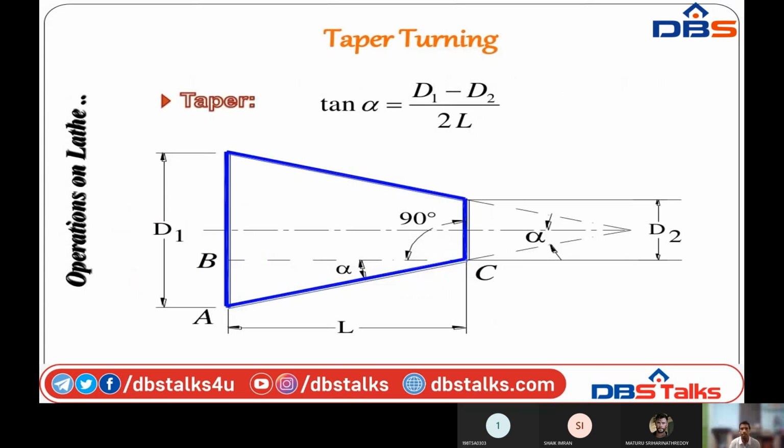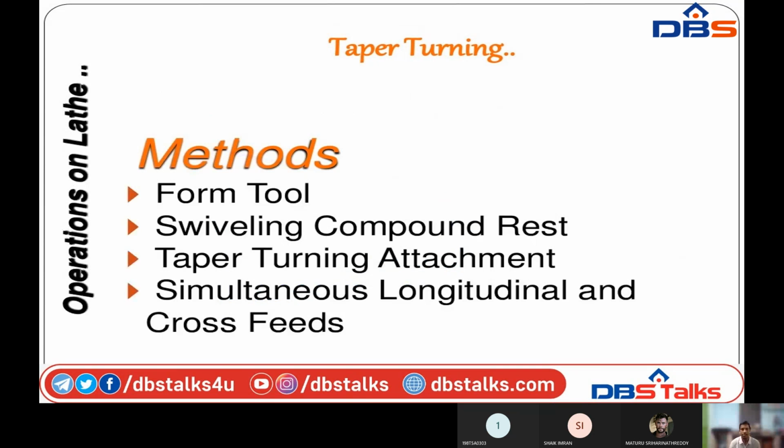Taper turning. Previously I discussed this. Taper turning means reducing the diameter of a given steel rod or anything. D1 is the originally taken rod dimension, that means D1 is the outer diameter. D2 is the required dimension. For example, I am taking D1 as 100 mm. The required dimension will be 50 mm. For that, D1 is 100 minus D2 is 50 mm, divided by 2. I am taking L as 200. Then alpha will be calculated. This alpha will be set on the carriage for taper turning operations. This is the taper turning operation. In taper turning, we are using a form tool here. Methods of taper turning: swiveling of compound rest, taper turning attachment, simultaneous longitudinal and cross feeds. These are the topics we will discuss later.